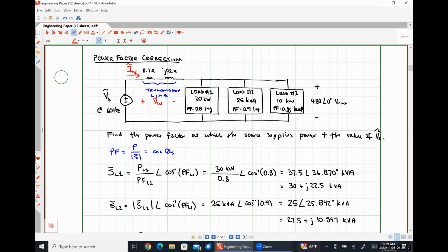So which of those two quantities can we actually solve for based on what we know currently? Well, I would argue it needs to be the current, because in order for us to find that voltage, we would have to do Kirchhoff's voltage law around this system, and we don't know what Vs is. So that's too many unknowns for us to handle.